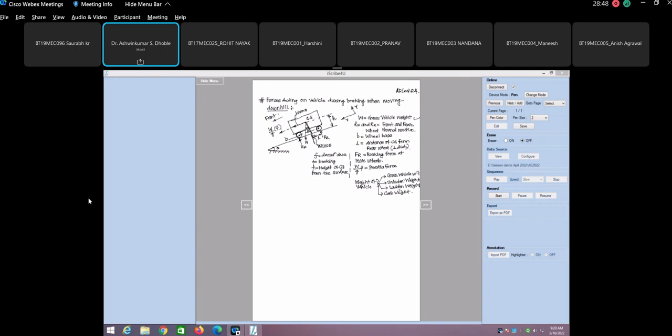मैं बोल रहा हूँ कि ग्रॉस व्हीकल वेट और लैडन वेट सेम है. अनलैडन वेट में आप ड्राइवर बैठा दीजिए और बाकी सब रिमूव कर दीजिए, that becomes your unladen weight. And curb weight में सिर्फ ड्राइवर भी नहीं, कुछ भी नहीं, बैगेज भी नहीं, जो वेट रहेगा that is basically curb weight. Laden weight और gross vehicle weight में कुछ फर्क नहीं है, because you have to consider baggage and passengers, all weights of all. And curb weight is only the blank vehicle, no driver, nothing else, that is curb weight.